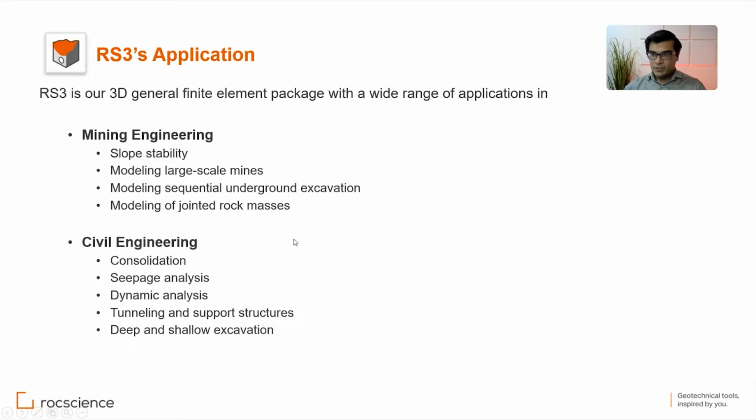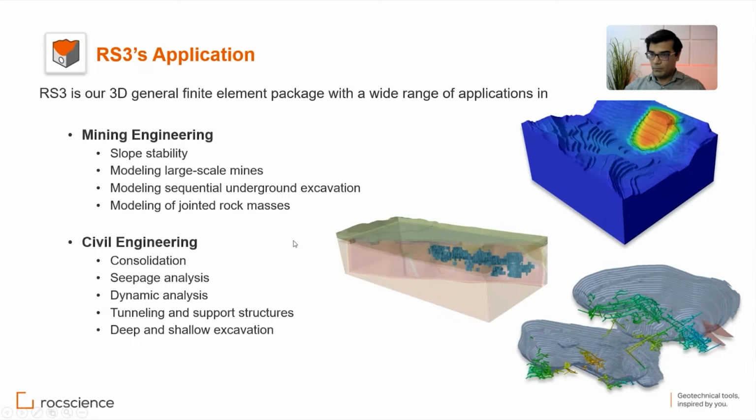RS3 is our 3D general finite element package with a wide range of application. I can categorize that into mining engineering and civil engineering. For mining, you can do slope stability, you can model large-scale mines, you can model sequential underground excavation, and now with the DFN, you can define the jointed rock masses.